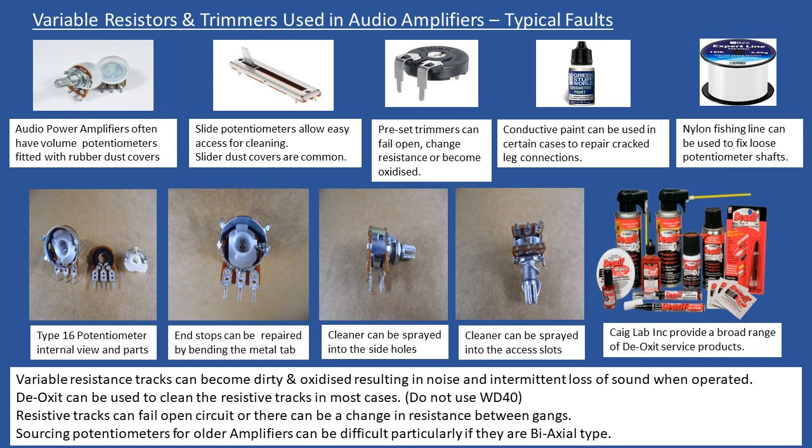So it's not unusual, for example, to use WD-40 to clean metal parts, which could be maybe rusty or stuck. The absolute thing you never ever want to do is use the blue can WD-40 and spray it into a volume control, bass, treble potentiometer.